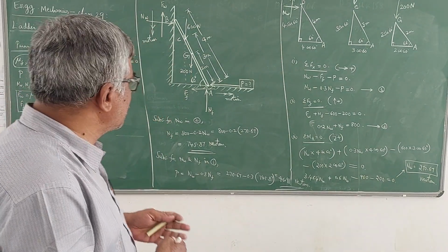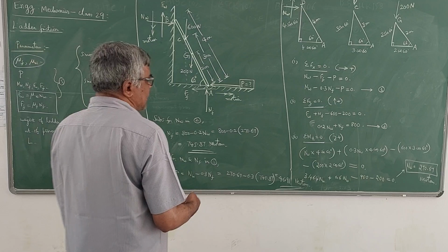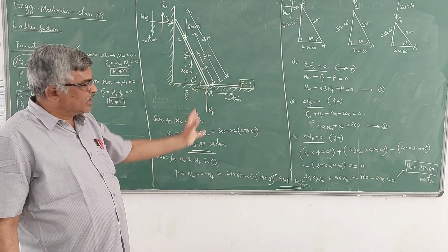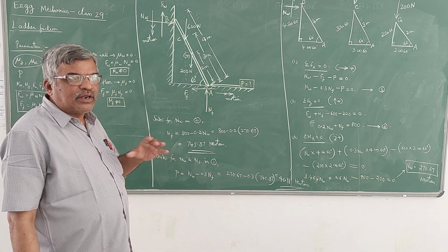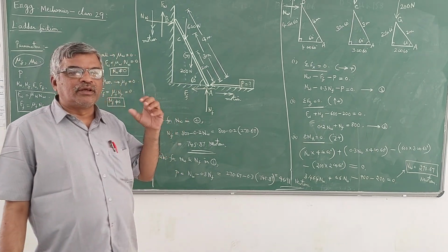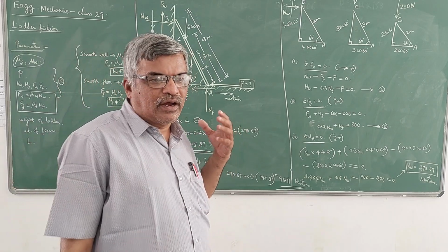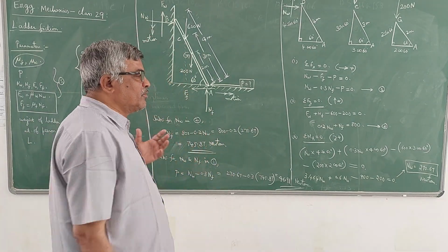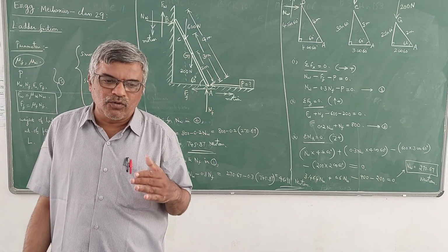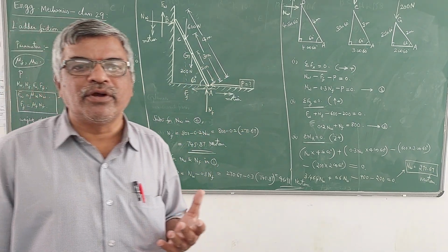So what I suggest is, understand the problem correctly, draw the diagram, and list out the data given in the problem. Only 3 unknowns should be there. In this problem, NW, NF and P are the unknowns because mu F and mu W are known. Ff and Fw can be found once we get the values of Nw and Nf.